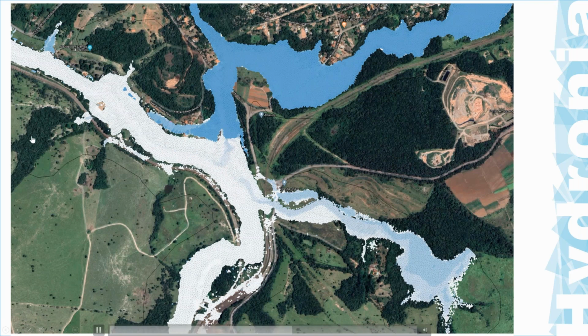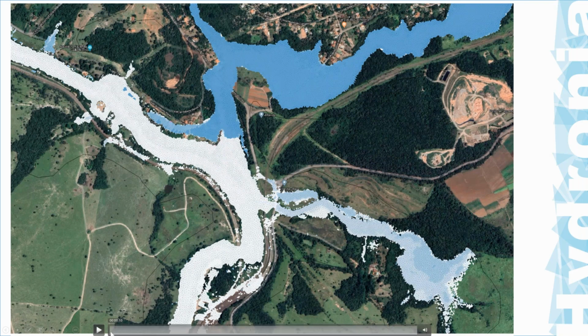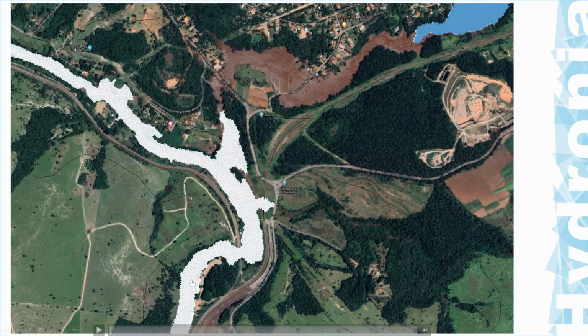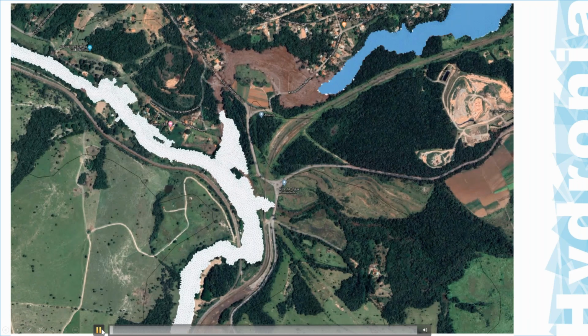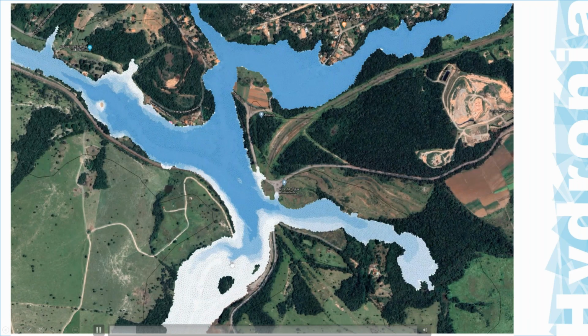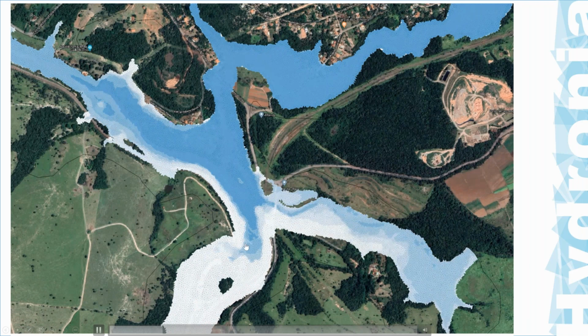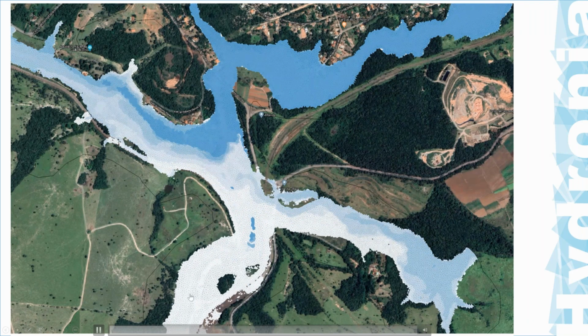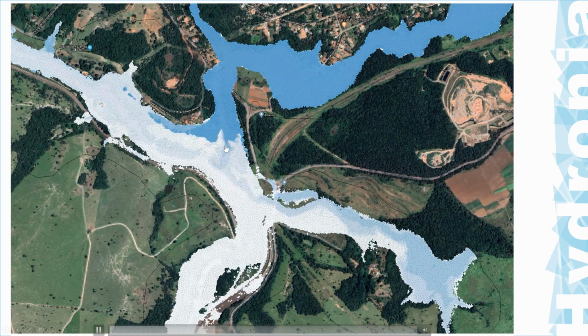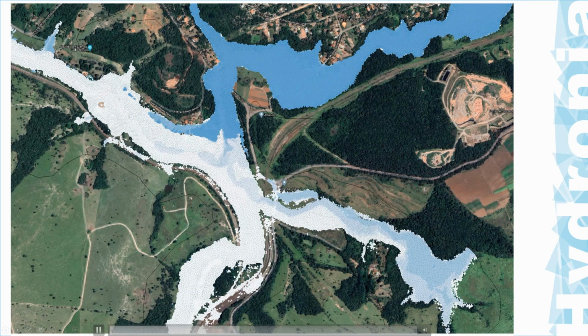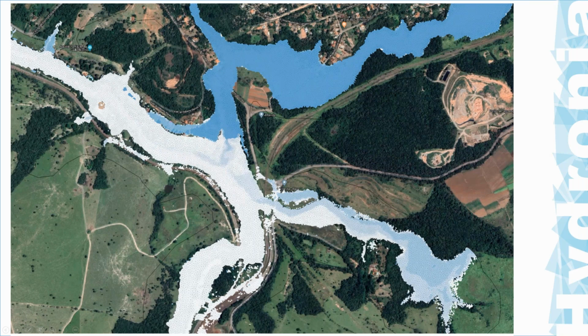So you see, eventually the flow passes again, but let me go back to the beginning so that you can see. Look at how this area floods because of the damming that occurs in the tailings. So it increases, you see, floods this area here. Part of the sediment gets into the river, but eventually the river prevails and washes out all the material and goes downstream. So this is something that you can get in the model.